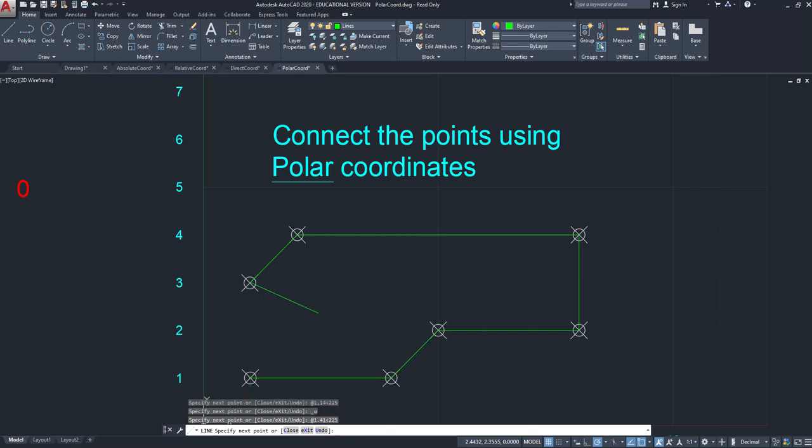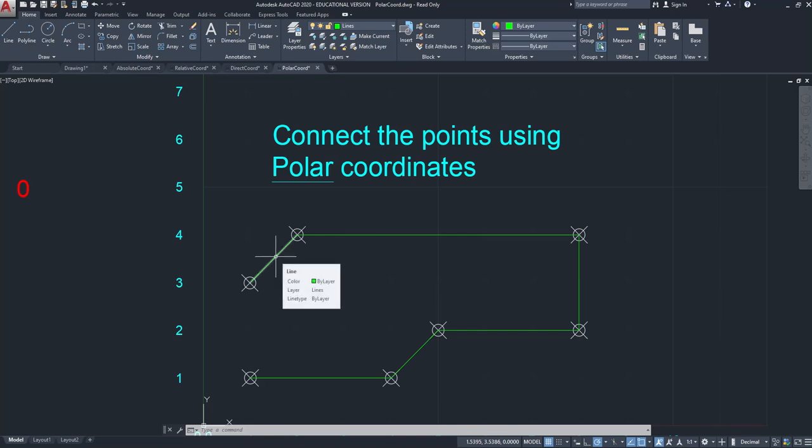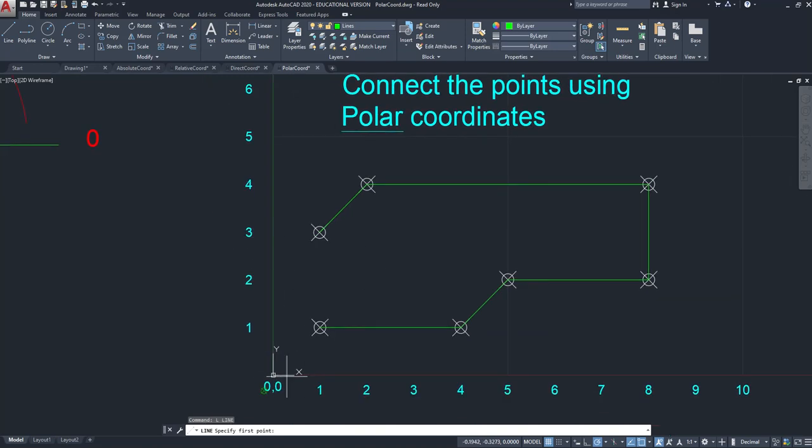Enter. Okay. 225 was the positive, right? So from here all the way to there is 225. But I also could have done a negative angle in this direction. What was that? 90 plus 135? Is it 135? 1 plus 45? Yeah, 135. Okay. I've hit escape and gotten out of my command. To reinitiate that, I'm just going to type L, enter. In the x direction, it's 1, 3. Let's type that. 1, comma 3, enter. I'm back where I need to be. 1, 2, 2, enter, and I'm back there. And I've got my shape.